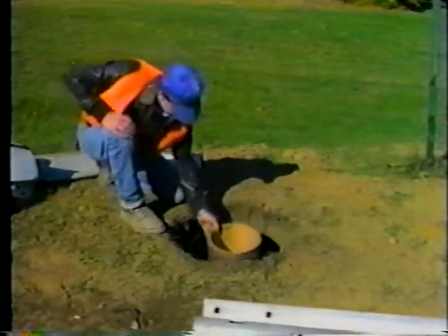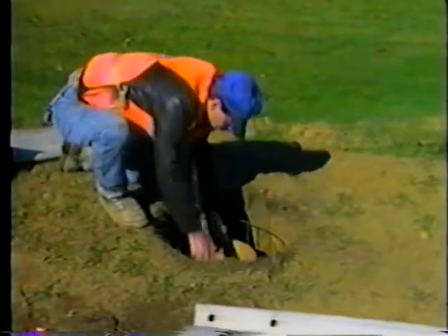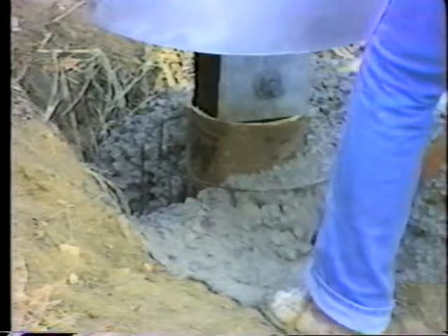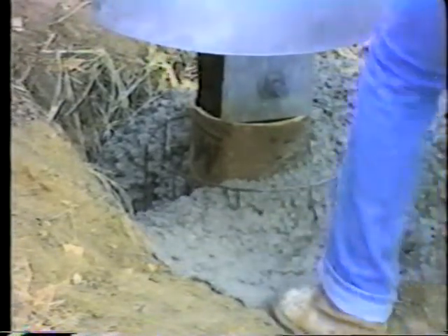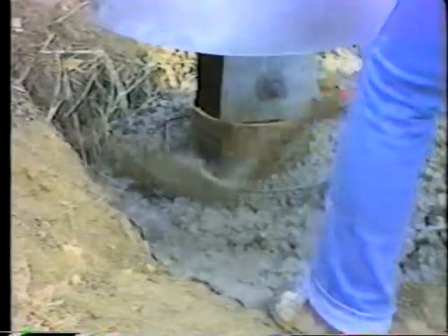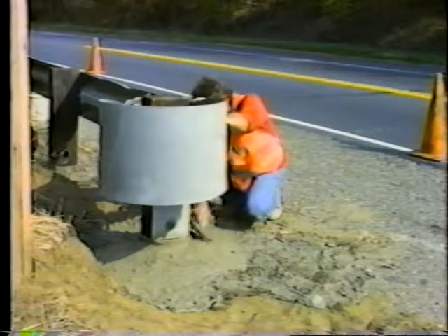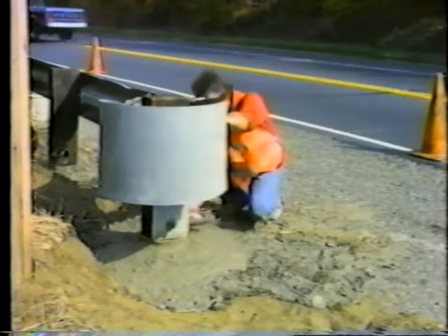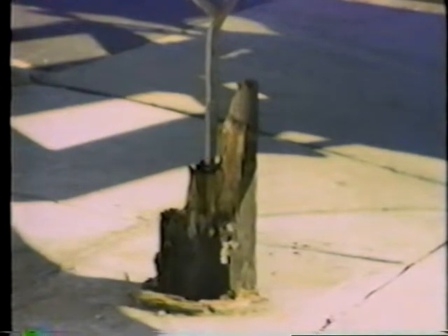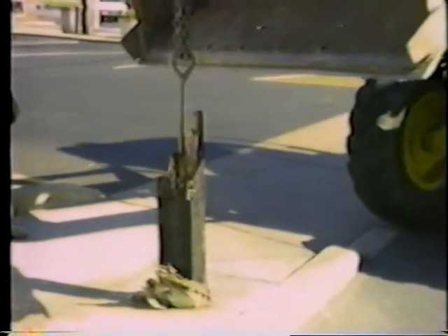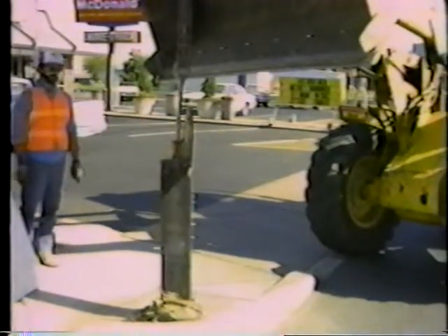Another solution has been to place a heavy pressed paper tube around the post when it's installed. The footing is poured around the outside of the tube. Now, care must be taken to ensure that no concrete is placed between the tube and the post. Once installed, the paper tube absorbs water from precipitation and is softened so that the post stub pulls out easily. Much of the tube comes out with the stub. The remainder can easily be removed from the hole since it does not adhere to the concrete footing. Stub posts can quickly and easily be removed from this type of footing, which meets installation specifications.